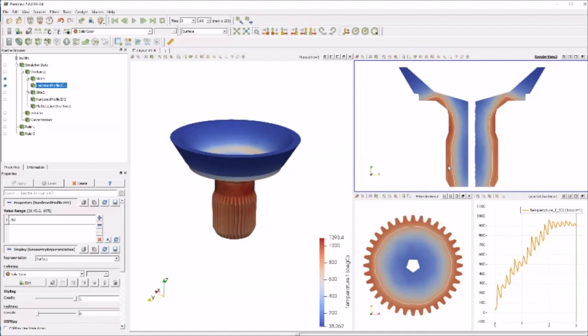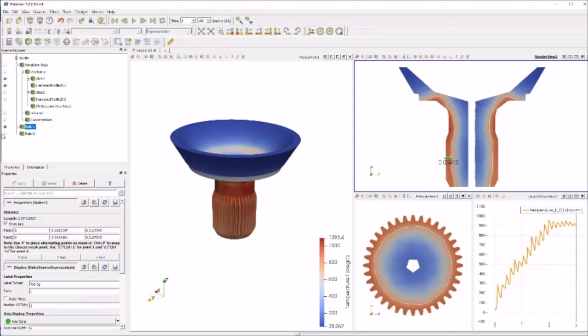The filter works based on temperature. You set up the austenitization temperature as a threshold temperature, and the filter just shows you the region which was effectively heated above this temperature. That means if your cooling or quenching was designed properly, most probably you will get a martensitic structure in this area. Of course, you can also measure it. You can see there are two rulers here.